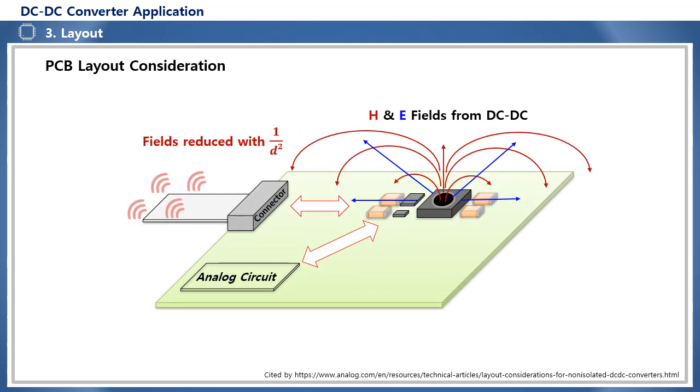Typically, noise from DC-DC converters and high-speed high-power switching circuits radiates through cables, which act as external radiation antenna paths. To block this potential radiation path, filter circuits are required at each cable connection point. This filtering prevents the H or E fields of the noise source from being coupled into the cable. Therefore, a minimum separation distance is required between the DC-DC converter, which is the noise source, and the connector. Analog circuits and precision circuits also require isolation or shielding measures to reduce the influence of E and H fields.